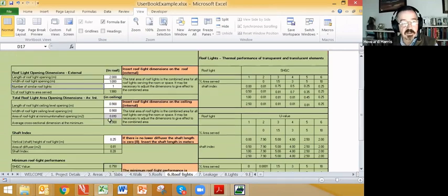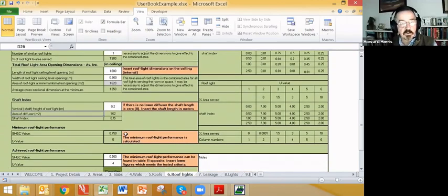At the outside dimension, it might be slightly smaller, so let's say 1.8 by 0.9, and if it had a depth, in other words, if it was multi-layer with a layer on the outside at the roof and also an inside diffuser with, let's say, a 200 millimeter gap between the two surfaces, we would find that the sheet calculates that an SHGC of 0.75 would be required and a U value of 5.